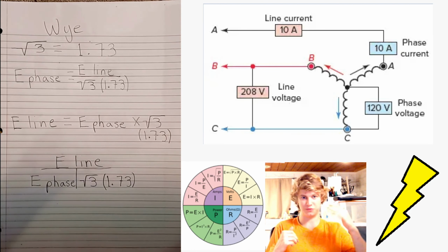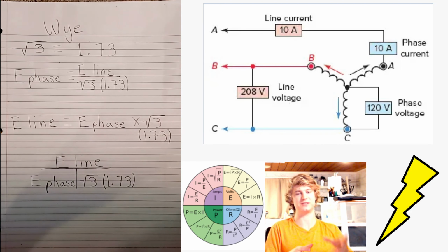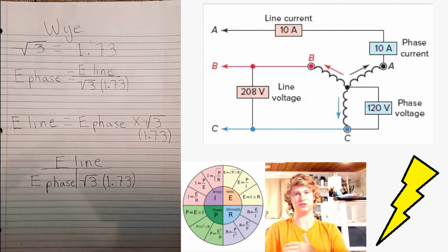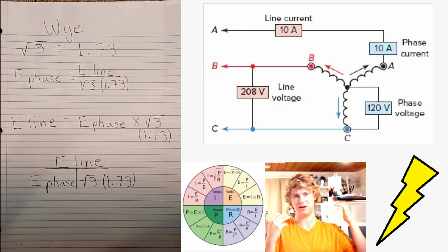Of course, all these voltages across each one of these phases are going to be equal. So in every circumstance, your line voltage is going to be bigger than your phase voltage. Very easy to comprehend because you're measuring the line of two different phases and you're combining those voltages, versus phase voltage, you're just taking the measurement of that single phase.